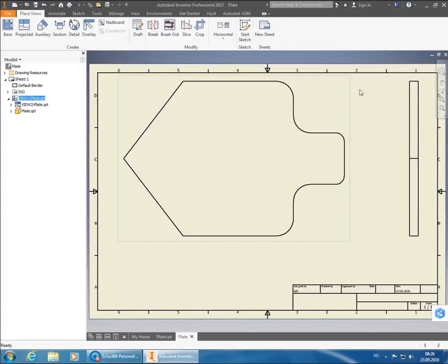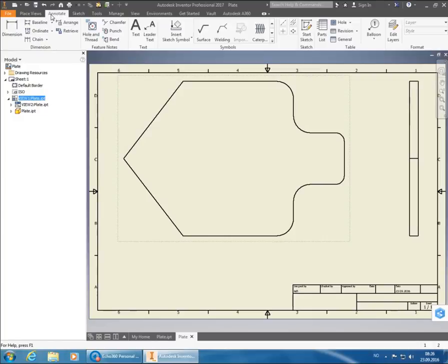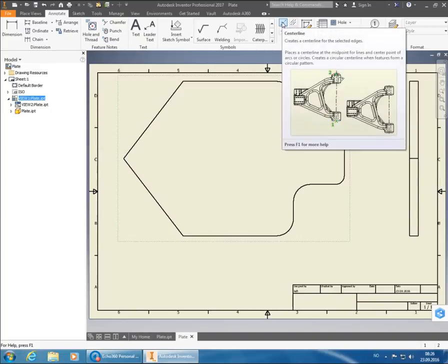I'll start off by showing where the symmetry line is on the drawing here. So I switch toolbar from the Place Views toolbar to the Annotate one up top there. And in Inventor, we just use the center line function, even though it's a symmetry line we're going to show, because the lines themselves look the same.